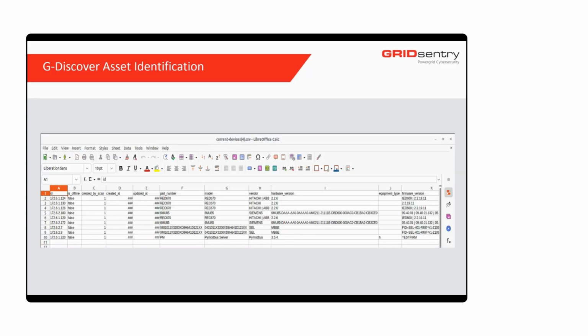And as I said, we have to have that particular combination information to harden your cybersecurity posture within the substation. So the part number and model number, as you see up here, is what you get from GDiscover: part number, model, hardware version, firmware version, etc., for each device that you have there. It's not OEM specific, it's OEM agnostic. You get it irrespective of the vendor. The only thing is that it's based upon the protocol, especially for a digital substation, it is much more on the 61850 side.